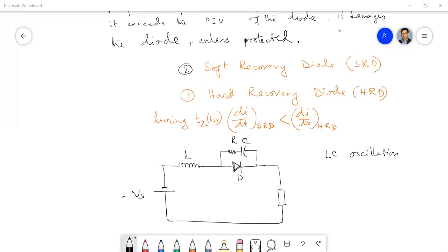Yes, sir. Can you tell me that question that I asked? The other name of n minus layer. Drift region. Correct. It's called the drift region. Can you tell me the objective of providing this drift region, because this layer is absent in normal diode? Yes, sir. This layer is absent in normal diode, but in power diode, N minus layer is provided to absorb the depletion layer created by the P plus and N minus substrate. Correct.